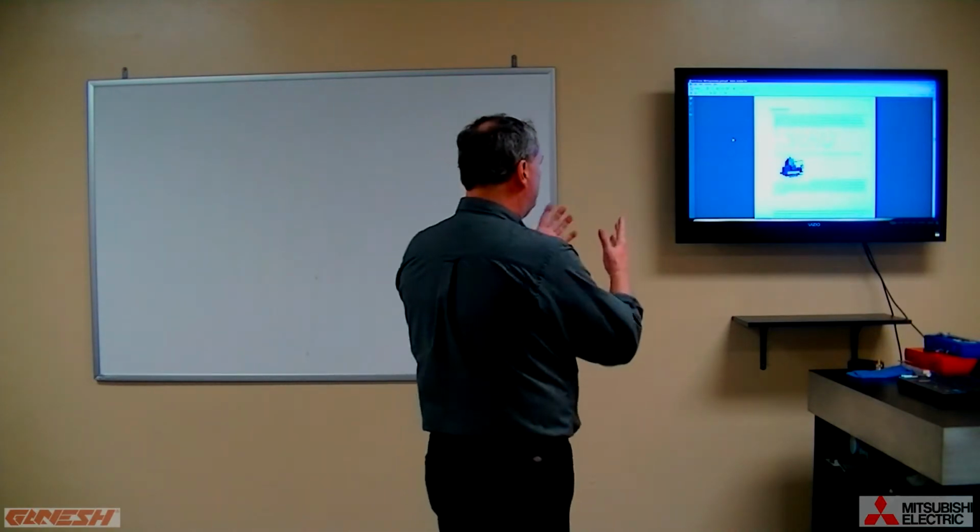So the concept of milling involves multiple axes. It involves our table moving from our left to right, which is generally our x-axis. It involves the table sliding in and out from you when you're standing right in front of it. That involves our y-axis. And then, of course, it involves the head of the machine and the tool going up and down, which is our z-axis. So the movements of the machine are a combination of all or one of the axes at any given time.